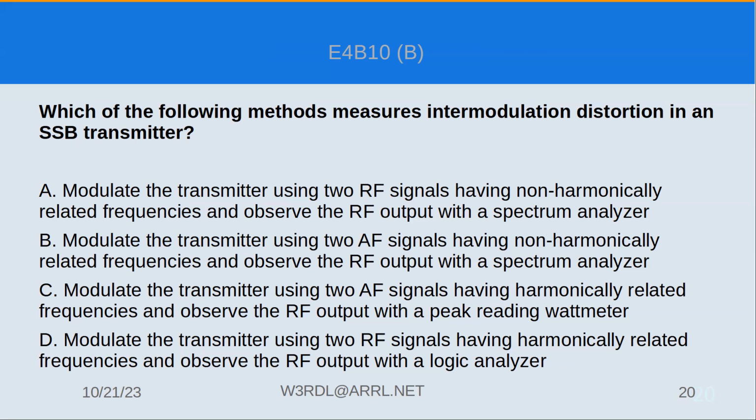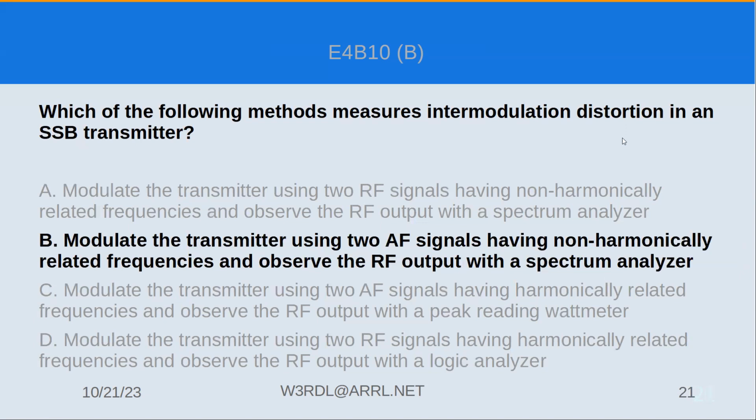So which of the following methods measures intermodulation distortion in a single sideband transmitter? Baker. Read this carefully. Yeah, you have to read the question or the answer very, very carefully. So it's Baker. Modulate. Yeah, bench. Right. Audio frequency not harmonically related. It's a very wordy one.